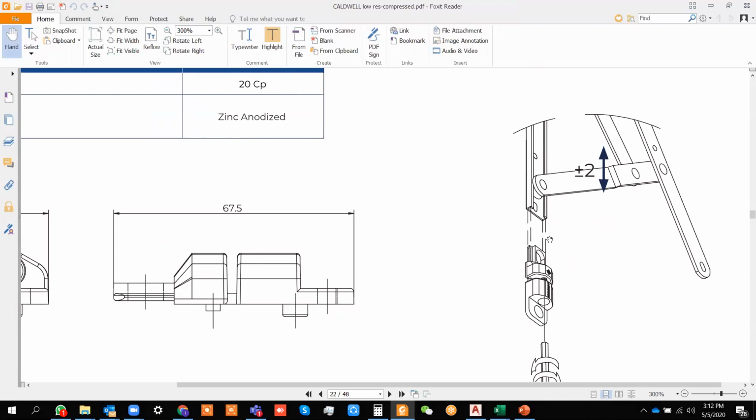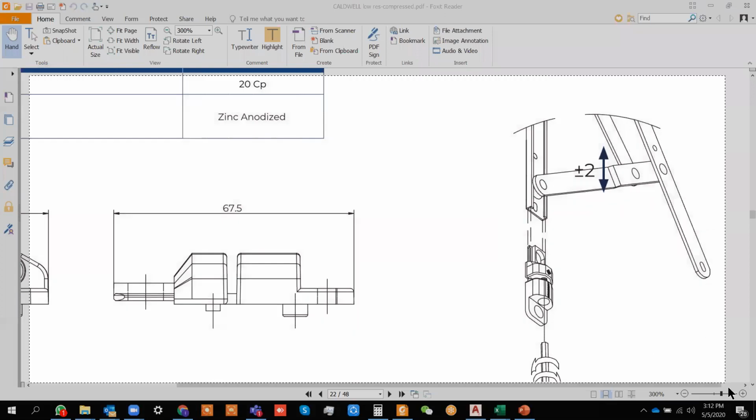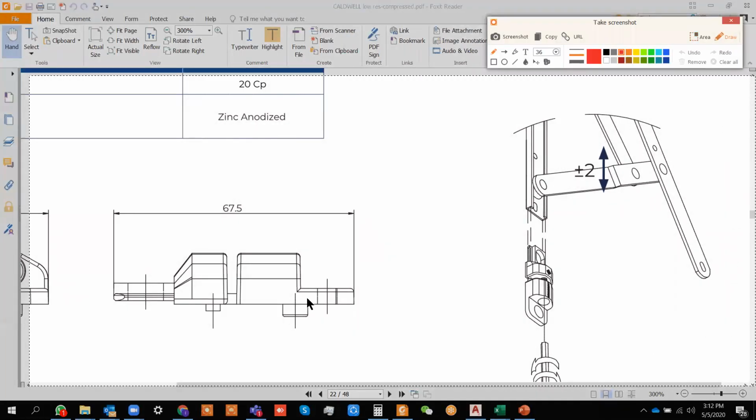Now you have to make sure that first of all you fix this in the outer frame. There is one hole; you have to make a hole in the area which I am highlighting over here. You have to make the hole in the outer frame and engage this area here, and after that you fix the screw here and in one more oblong hole in both the arms, and check whether the window position is correct. If the window position is correct and there is no need for adjustment, then you can fix the other holes and confirm the position.